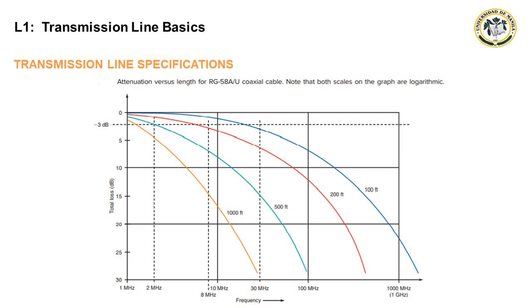It shows attenuation curves for four lengths of a popular type of coaxial cable. It should be clear why it is important to use a larger, lower loss cable for longer runs, despite its cost and handling inconvenience. Finally, a gain antenna can be used to offset cable loss.